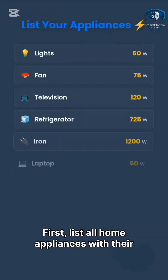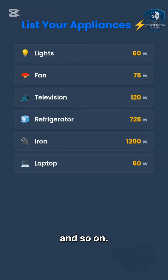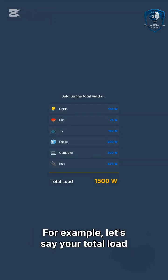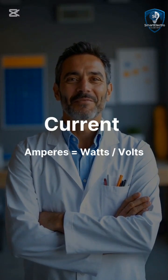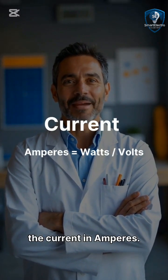First, list all home appliances with their watt ratings: lights, fans, TV, fridge, iron, and so on. Next, add up the total watts for all appliances you plan to power simultaneously. For example, let's say your total load equals 1500 watts. Then, divide this total wattage by your home's voltage, typically 230 volts, to find the current in amperes.